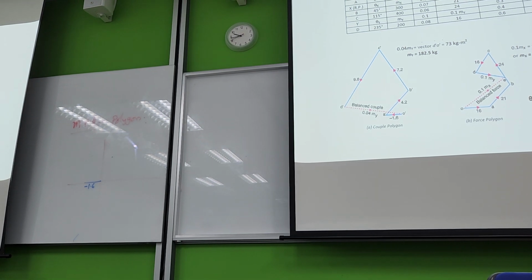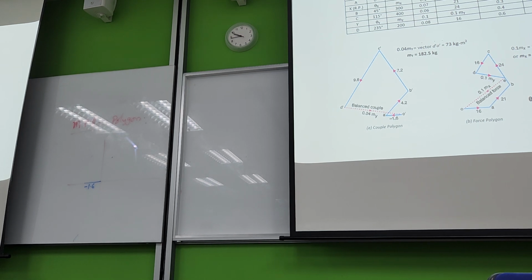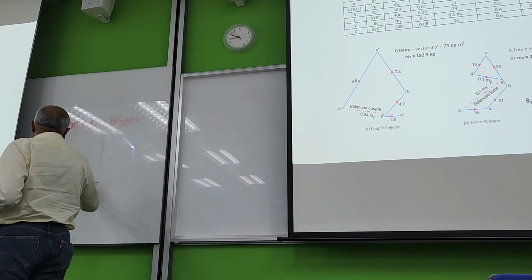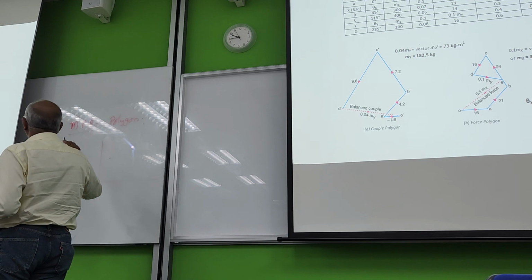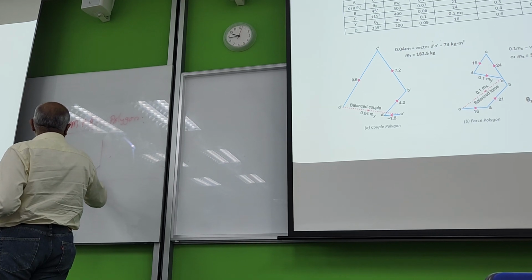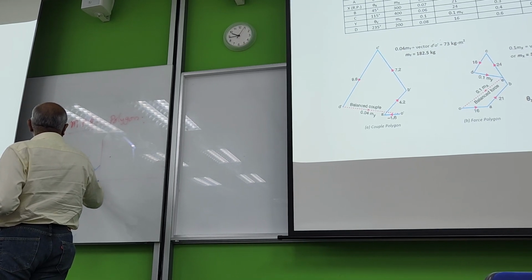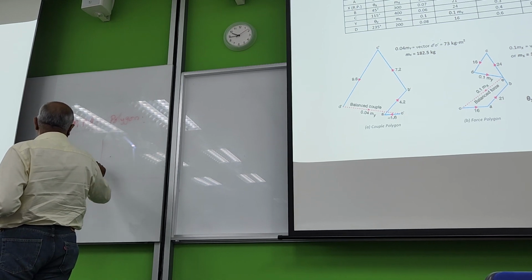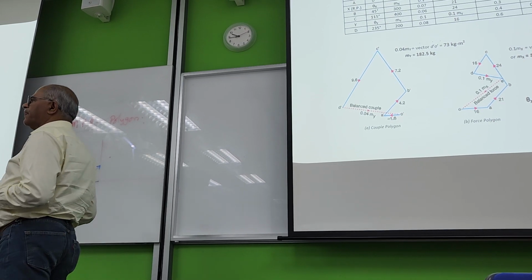Now from the tip of that, plane B, the value is 4.2 and the orientation is 45 degrees. So from the tip of this, at 45 degrees, you plot a magnitude of 4.2. So this is the MRL for A plus this.